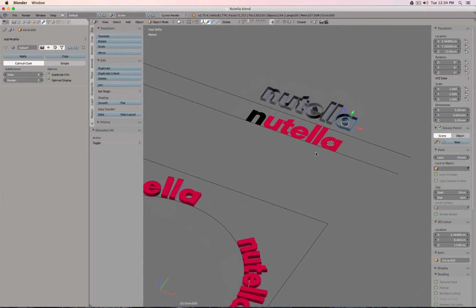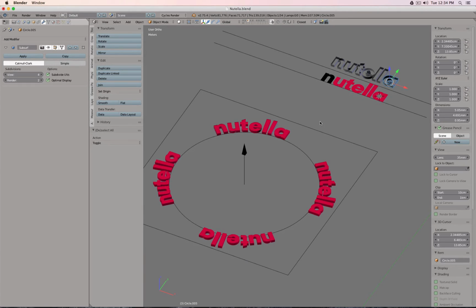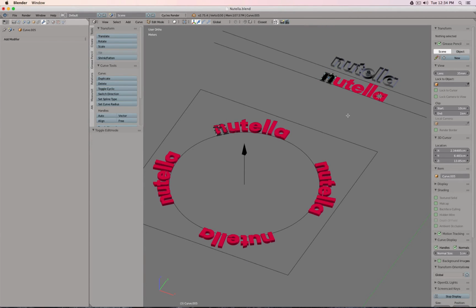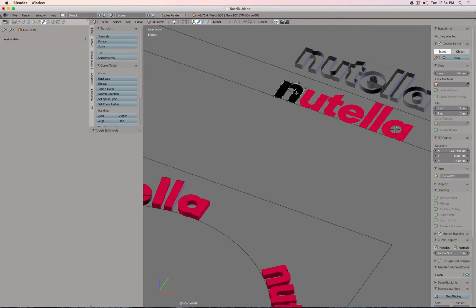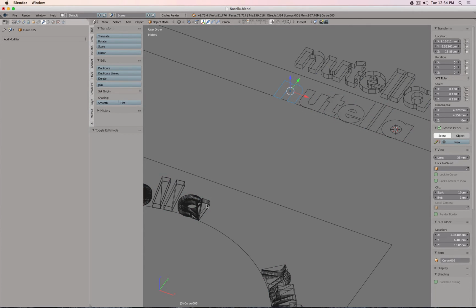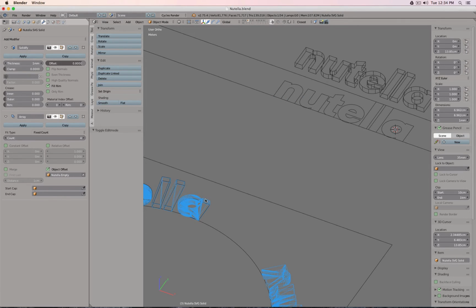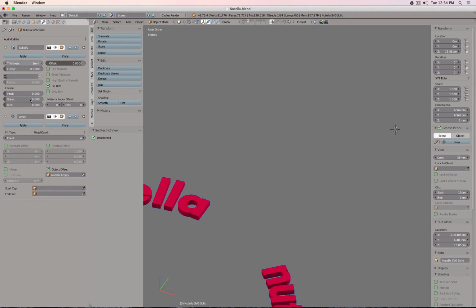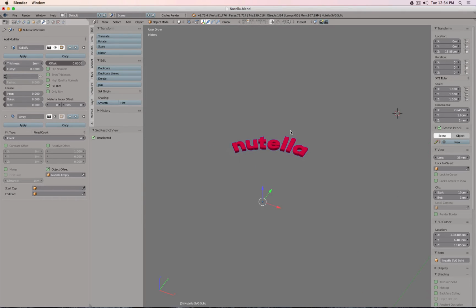Because this is a polygon mesh and we resculpted the letter, in Fusion we can also adjust the geometry when we go into the T-spline module. Plus, we can, for example, give a thickness to these letters, like what you see here with the solidify modifier.